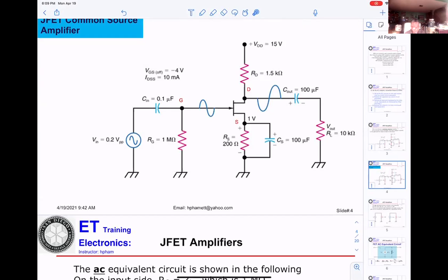Okay, at the D, right? Correct, you get two voltages. One is the DC bias. So you do get a DC bias from there to ground, and you also get an AC voltage, correct? You get two voltages, one AC, one DC. Perfect, thank you. You answered my question.